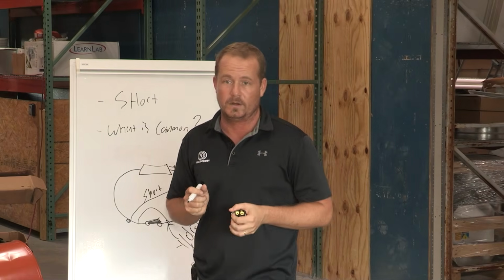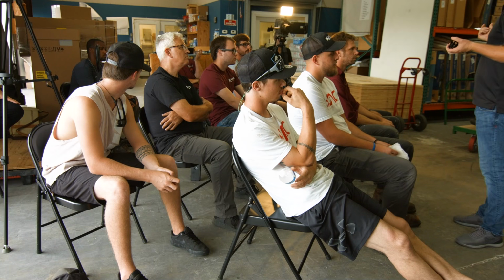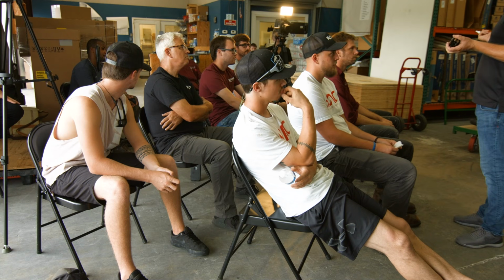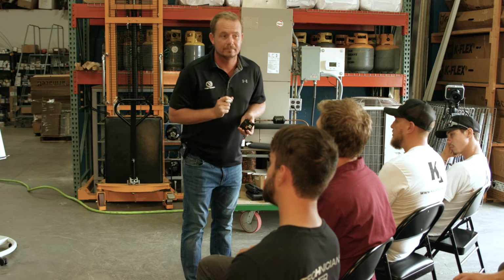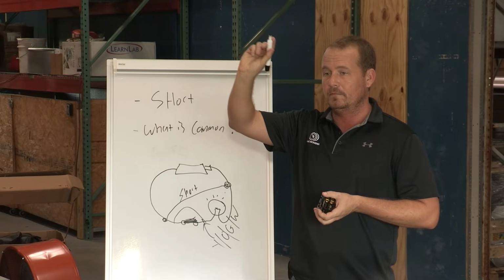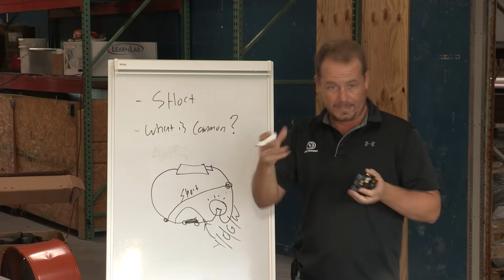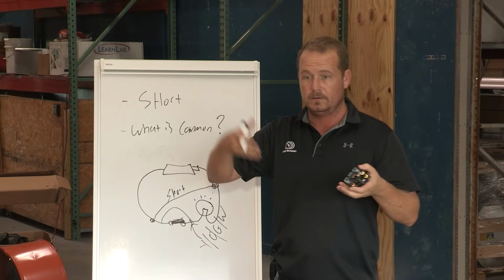On a low voltage circuit, what is common? Jessica, low voltage circuit, what is common? You know. It's the other side. It's the other side of the 24, but where does it end at? Where is the ultimate point where common connects? Ground. Kind of. It can. But it's actually the transformer. It's the other side from hot on the secondary side of the transformer. Right? So that's where the 24 volts comes from. One side is common, one side is hot.